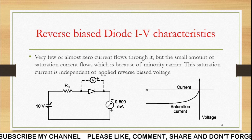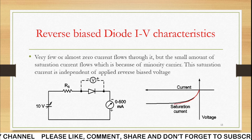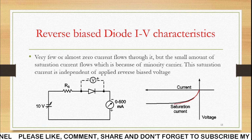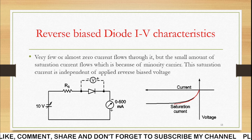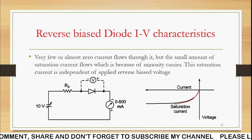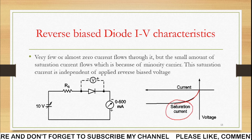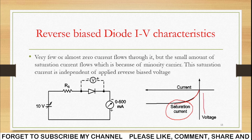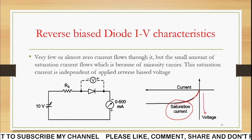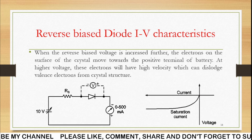So this will be a very small amount of current, and that is due to the minority carriers available in the PN junction diode. So that's why we are getting a current that is due to the minority carrier, and that's why it is called as a saturation current. So this is independent of the applied reverse voltage. So whatsoever the reverse voltage is there, the current will slowly increase and it will remain as it is.